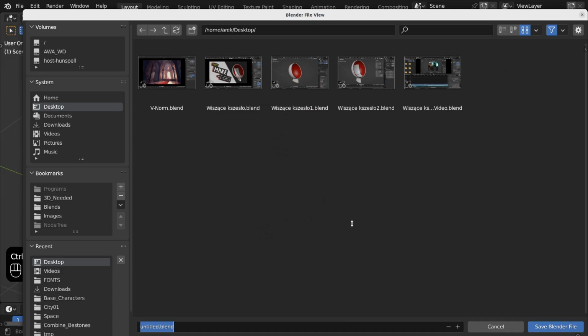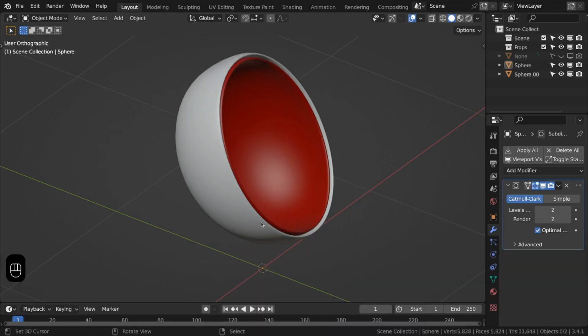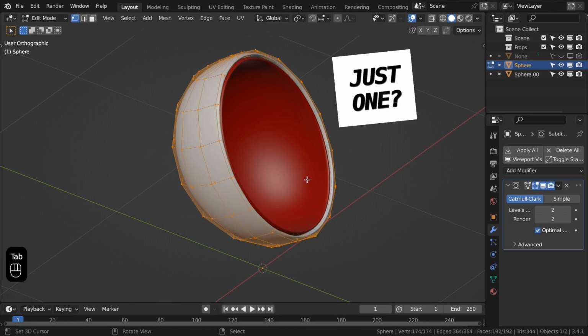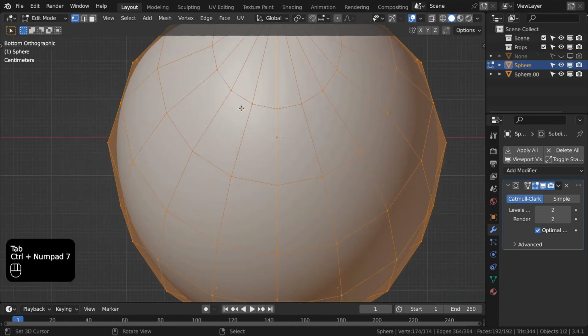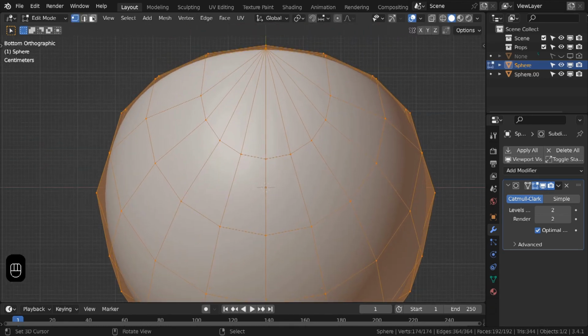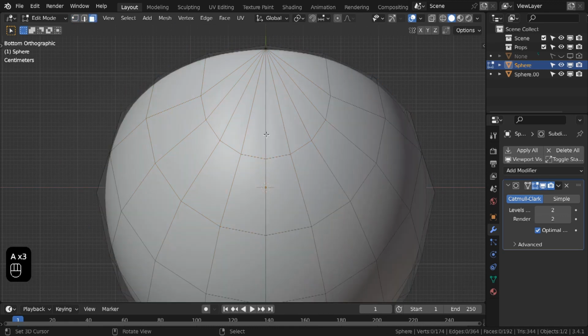We can save our file. And now let's add a leg. So Ctrl 7, go under face select mode, and with the left mouse button or with B, you can just select. Left mouse button is in this case just fine, like a selection like in Windows.